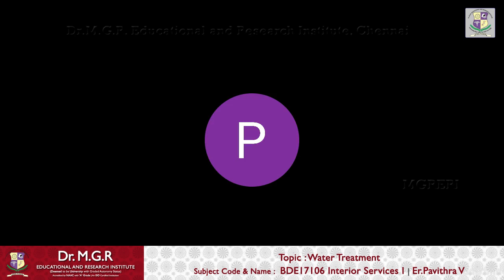After that, the grid system, which is also called the interlaced system or reticulation system, mainly consists of mains, submains, and the branch lines. After that, the ring system, which is also called the circular system, in which the old system is surrounded by the mains, and after that the mains are divided into branches.